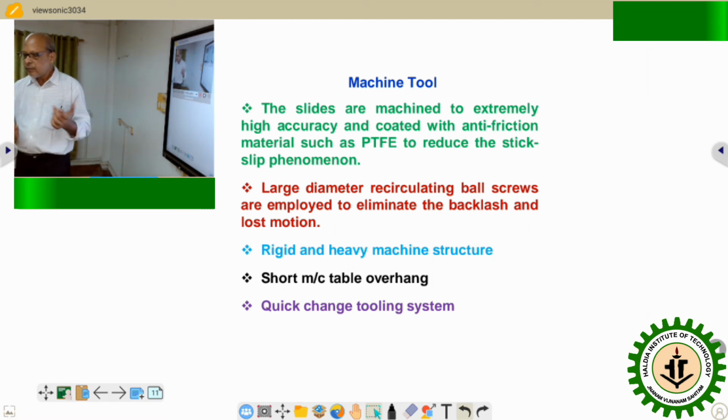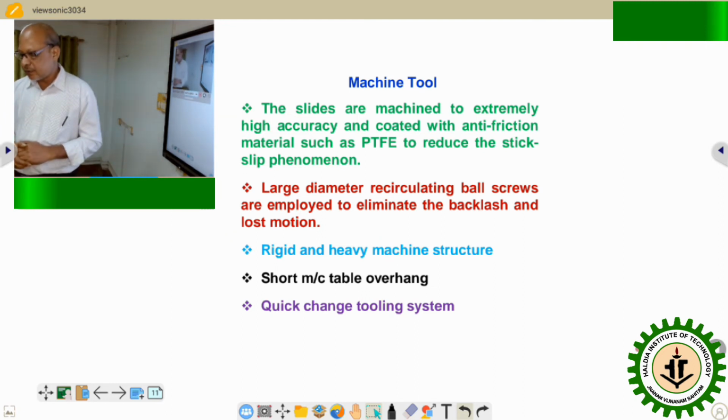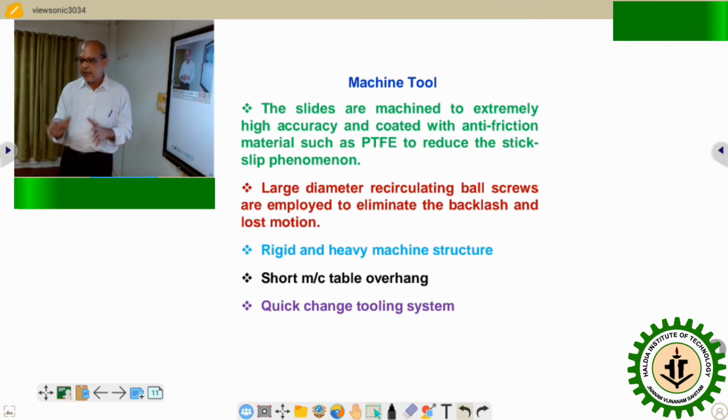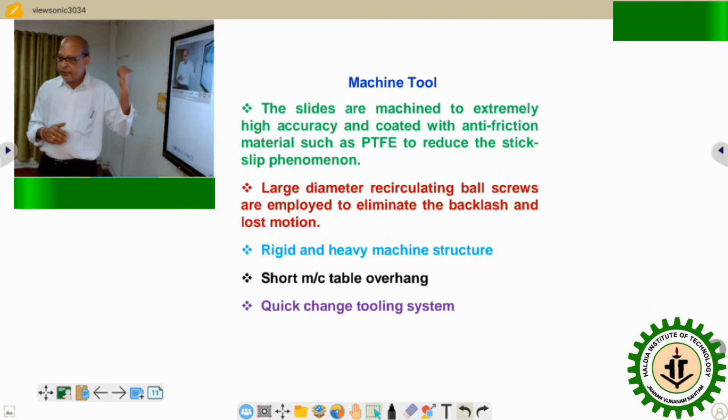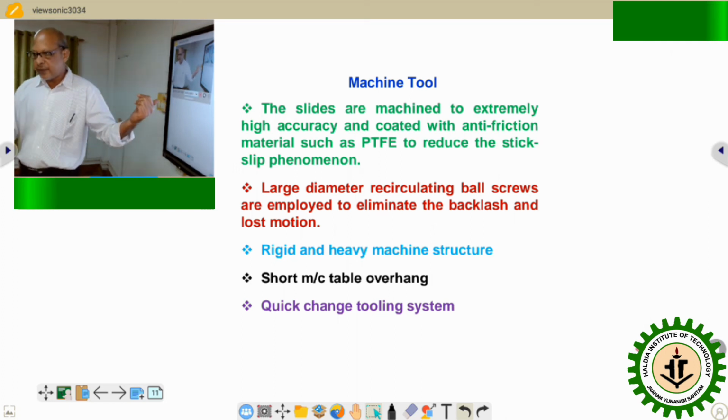If you apply higher levels of feed and depth of cut, it is accompanied by an increase in cutting force. So there are restrictions; you cannot increase feed and depth of cut without limit. Similarly, if you increase the cutting velocity, force multiplied by velocity gives the power. So if you want to employ higher levels of cutting velocity, feed and depth of cut, you will definitely achieve a higher MRR.